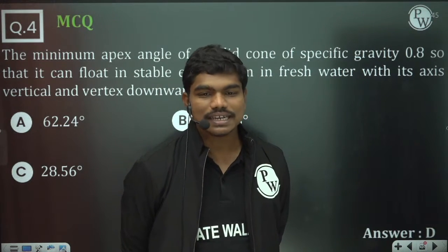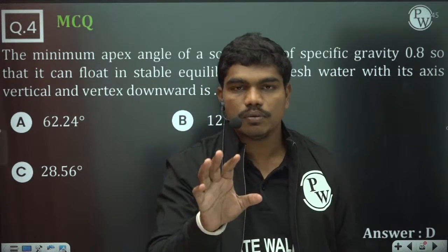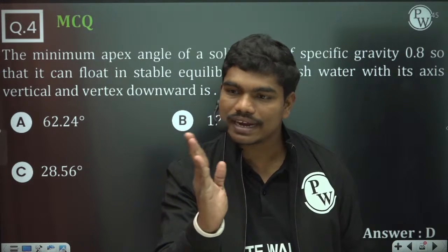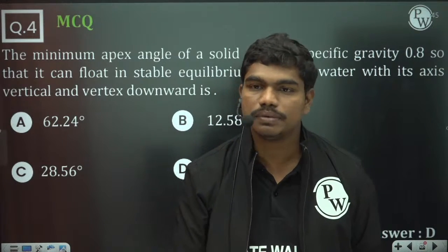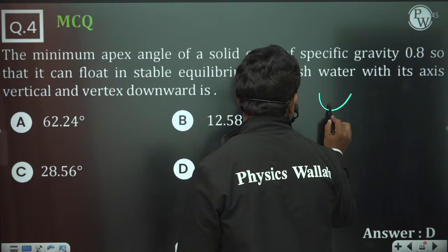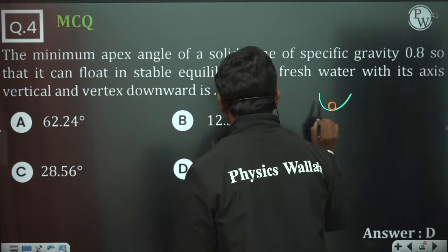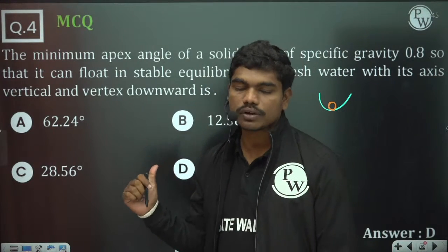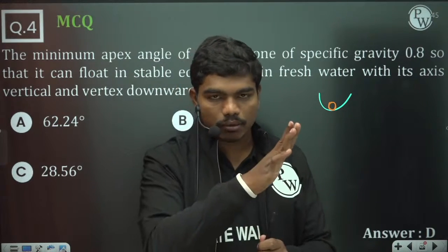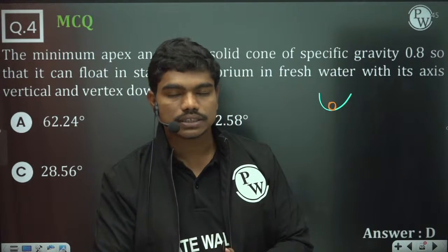Okay, fine. So basically, stable equilibrium is that configuration of equilibrium when you slightly disturb the position of the body from its equilibrium, the body again tries to come back to the same equilibrium condition. Let us suppose, for example, you have a bowl kind of thing, in this you have a spherical ball which got settled here. Now if you slightly disturb this ball, what happens? This ball again comes and occupies the same position. So stable equilibriums are those where even if you disturb the body, the body will again try to come back to the same location. So that's stable equilibrium.